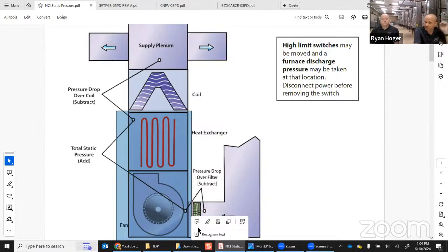In contrast, if you had what Carrier and Bryant call a fan coil, or what most people call an air handler, the filter is physically inside the cabinet. So in that case, the fan system, the internal pieces of the cabinet, and the filter are all internal, and external would mean just the ductwork on that kind of project, because your coil and your filter are inside the box. But furnaces is what most of you guys do, so we'll stick with that example.